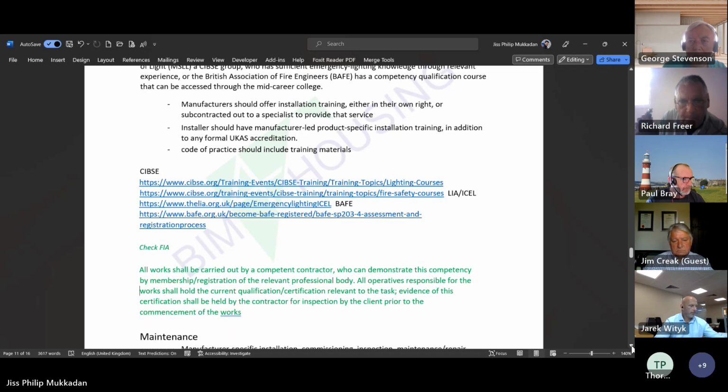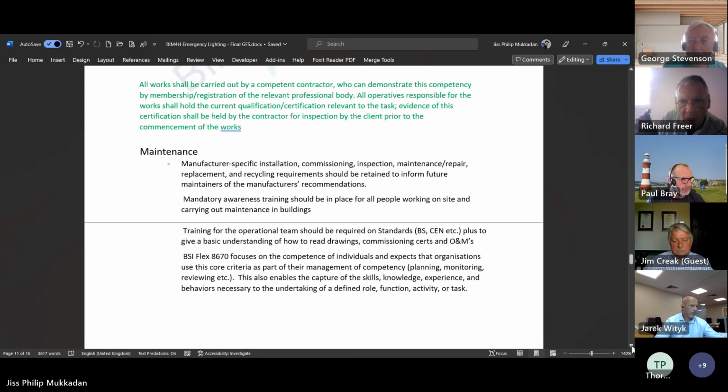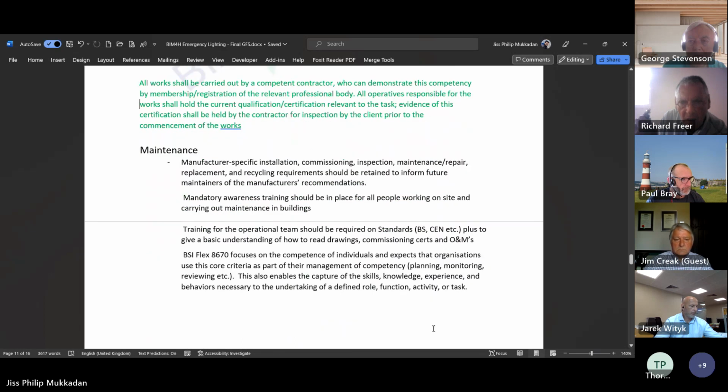Okay, what have we got underneath that? For maintenance. What about things like frequency? Has that been changed at all with the legislation? Is it how frequently you are supposed to test it or maintain it? Well, effectively, your test levels go daily, monthly, yearly, and there will be a 5-yearly test as well. So you test different things. So every day you're supposed to check that the green LED charge indicator is lit, for example. Yep. And what about maintenance, Peter?